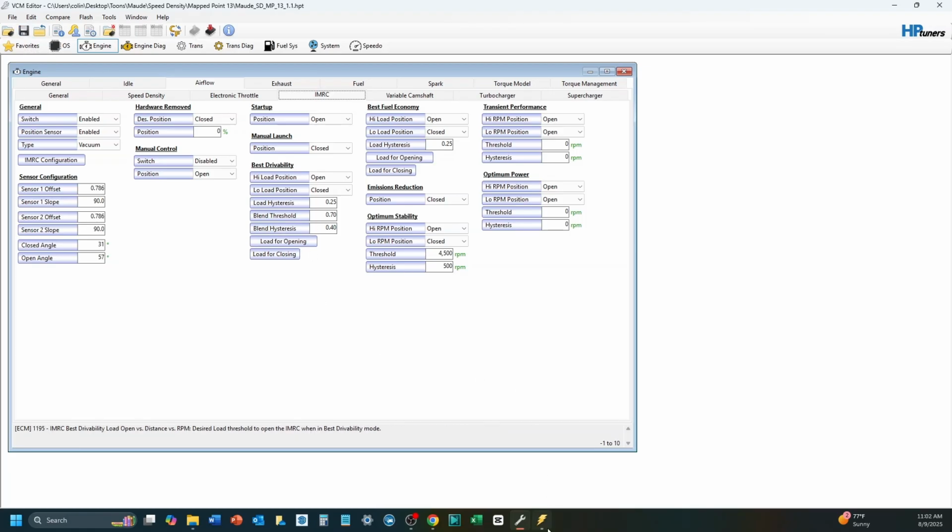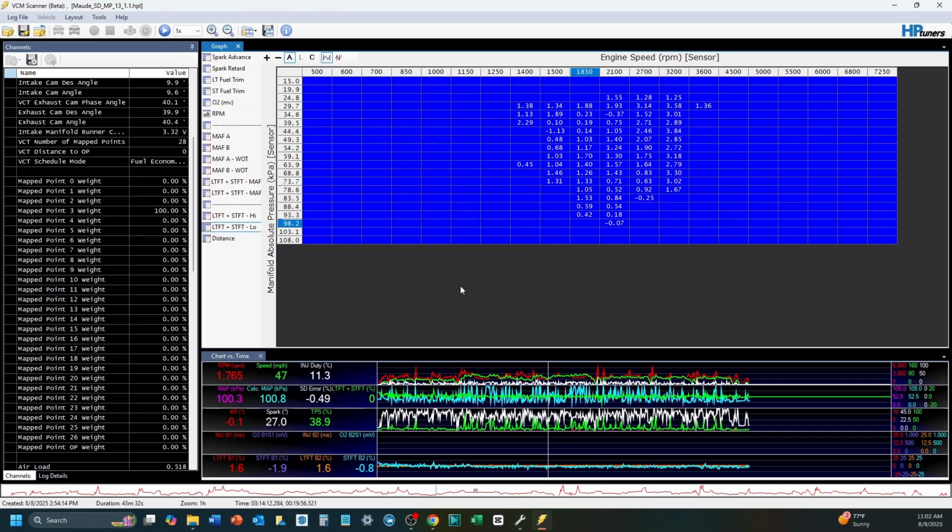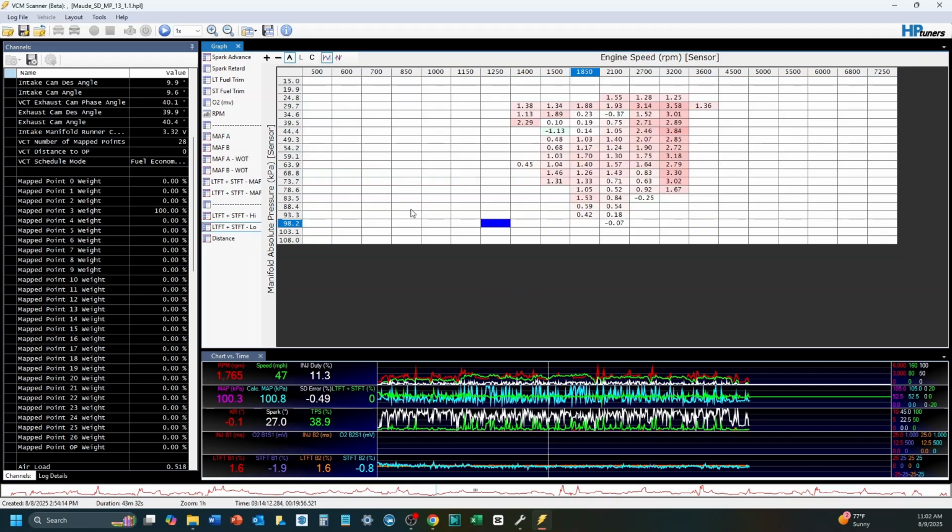And that, well, now you can let rip, and you would come over and do the next set of your logs, right? So, pretty easy, pretty good. I've gone through half of my speed density tables at this point and done all this. Once that is all complete, then you will see your trims have pretty much lined up, and you can think about the optimum power tables.